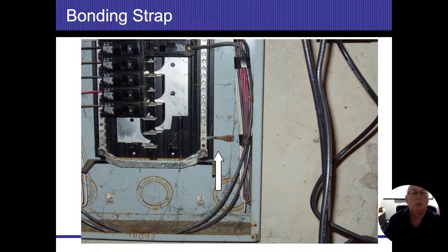If the utility companies, such as the phone company, cable company, satellite dish, they all have to ground their items as well. So they may be going ahead and grounding to the plumbing pipes. They may go ahead and ground to the meter box outside. Whatever it is, the expectation is there that those items are grounded. And not only that, but if somebody is outside and they're going to be touching the plumbing pipes inside and something's disconnected, we want to make sure, because all those pipes are metallic.